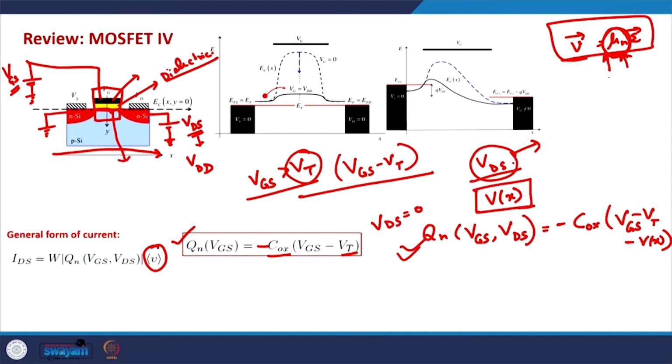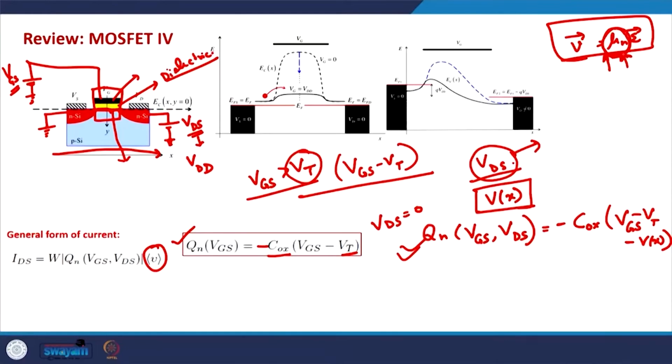In terms of the density of states and the number of modes, even this mobility can be represented. In the case of ballistic MOSFETs, this notion of mobility is not a fundamental notion. We need to start with the density of states and the scattering properties of the channel, and then we can define the mobility. But in long channel MOSFETs, the velocity at which this charge moves depends on this, and in the linear regime we have seen this already.